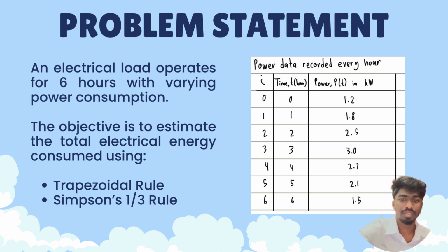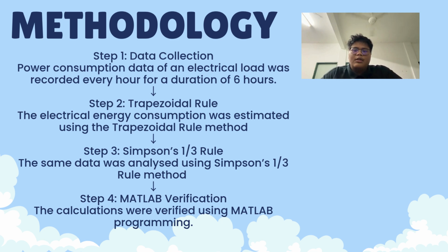Thank you. Okay, next I will explain the slide on methodology. This slide shows the methodology used in this project. In step 1, the power consumption data of an electrical load was collected every 1 hour over a period of 6 hours. We use this data as the input for the numerical analysis. Next, in step 2, the trapezoidal rule was applied to estimate the total electrical energy consumption.